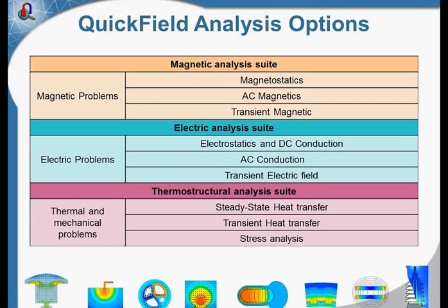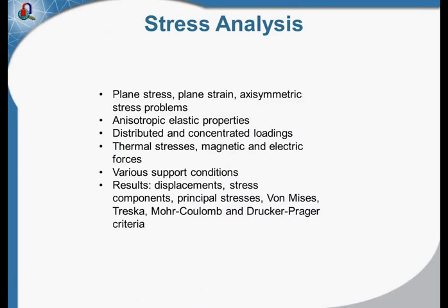Today we will discuss stress. The stress analysis model allows you to simulate plane stress and strain, axisymmetrical stress problems, including anisotropic, orthotropic elastic properties. It allows various types of loads, thermal stresses, various support conditions, and the post-processor shows results as displacement, stress components, principal stresses, and various failure criteria.